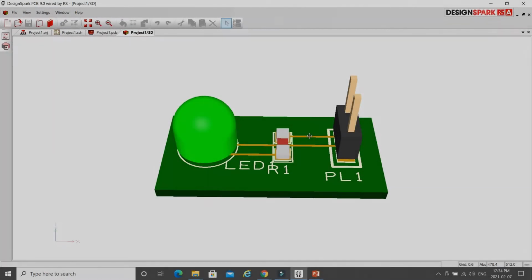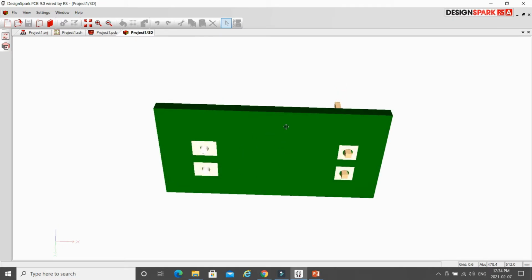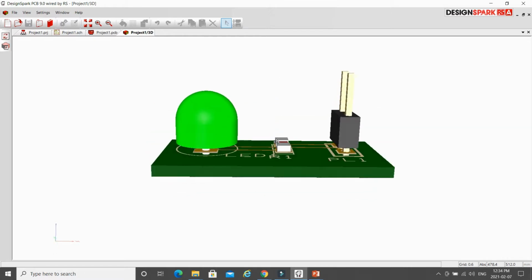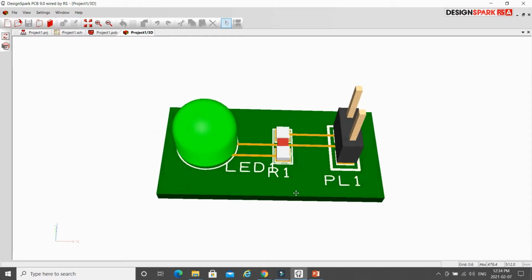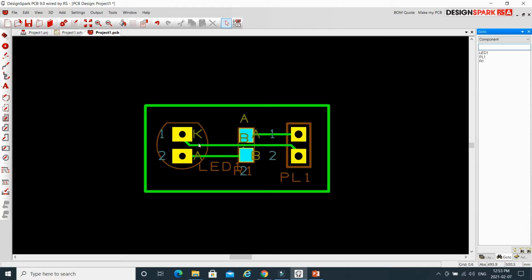If you look at the board closely, you will see that the tracks only appear on the top layer, but not both layers of the board as we defined at the beginning. And when we design a compact circuit board, we should try to put the ground away from the power and signal tracks to reduce interference and noise. Thus, we should put the ground track on a separate layer of the PCB. In our case here, we can put it on the bottom layer.